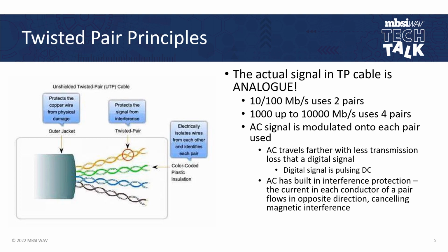What happens is if I send a pulse into a cable, that pulse, as it travels down the cable, the capacitance and the inductance of the cable itself, a little bit of electronics here, will tend to round off that signal. So if I have a square wave coming into the cable, I will end up with much less than a square wave coming out of the cable. And so that limits the distance that I can send the cable and recover that data from.